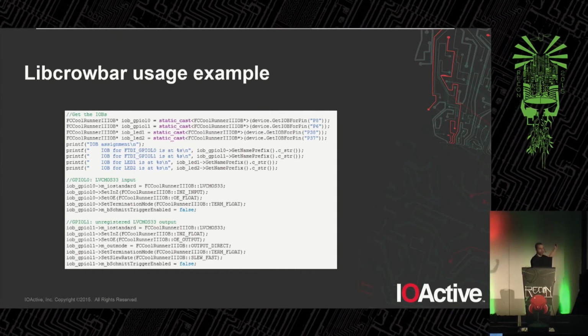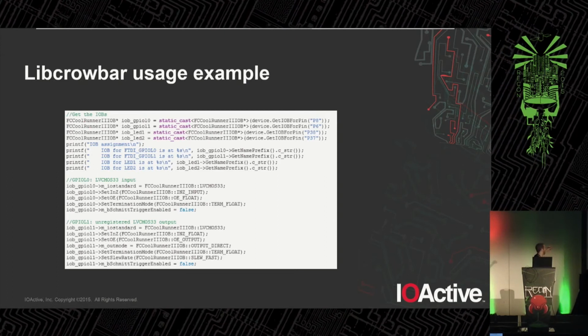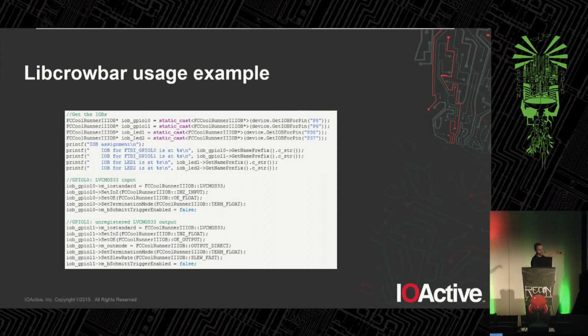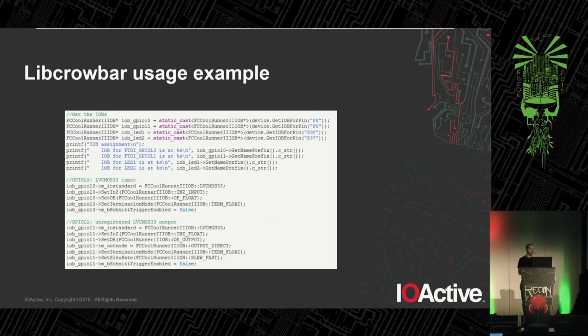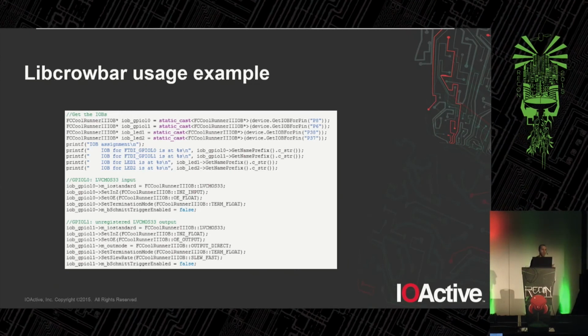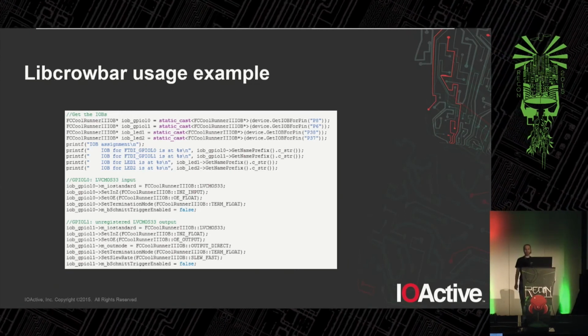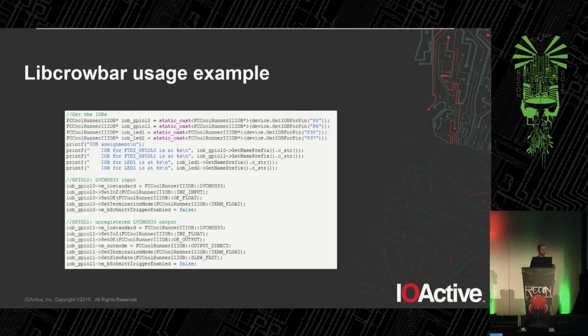These are all bits in the macrocell that I was able to figure out. There are still quite a few related to clocking that remain unknown at this point. And then there's quite a bit more going on below this. I can pull up full source if anybody's interested in looking at it. But the end result is that I can go from an in-memory technology mapped netlist created like this as C++ objects. I can then place and route this, produce a valid bitstream, flash the device, and have it work.